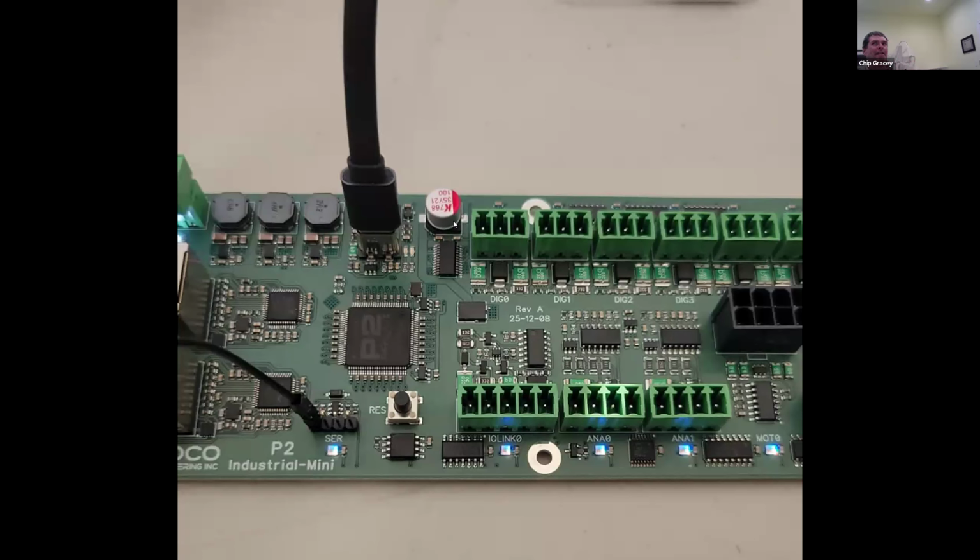I thought that was the case, and I confirmed it by getting a little thermal camera with the macro view. And I could see it was like 102 degrees right in that corner of the chip, right here. See, those are the 4 pins right there that attach over to this H-bridge. And sure enough, there's a hot spot on the thermal camera right about there, right where the die is that supports those 4 pins.